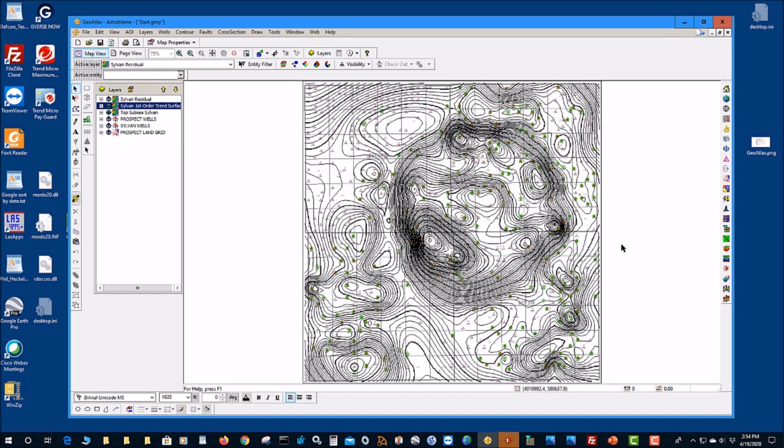Another place where that could really come in handy is if you happen to do a lot of either hand contouring or hand editing of machine generated contours to generate your geologic concepts, your geologic maps. If you do that with a couple of surfaces and you want to get an isochore, a thickness map as a result from your interpretation, you would take your edited maps or your hand created maps, do a contour to grid operation. So you end up with two grids based on your interpretation of the data, and then subtract one from the other to get a resultant grid, a grid operations layer, as it were, that reflects the thickness based on your interpretation. That would be another common use of grid operations.